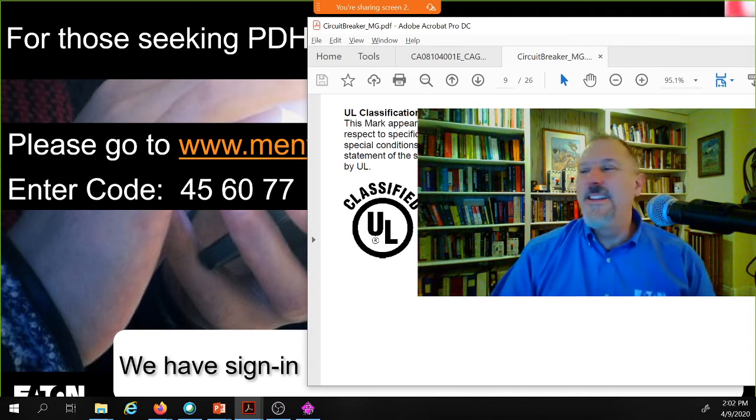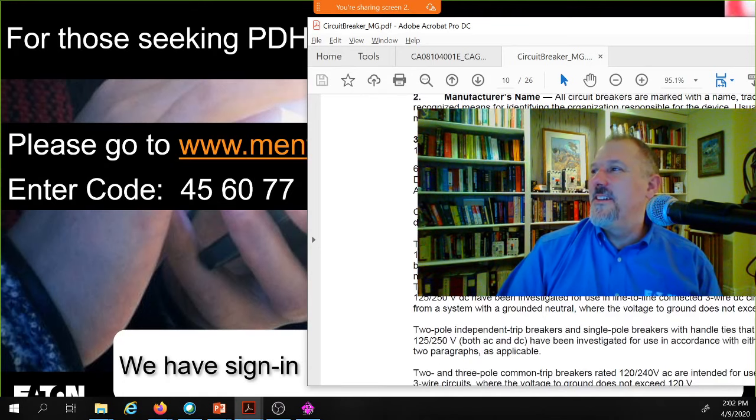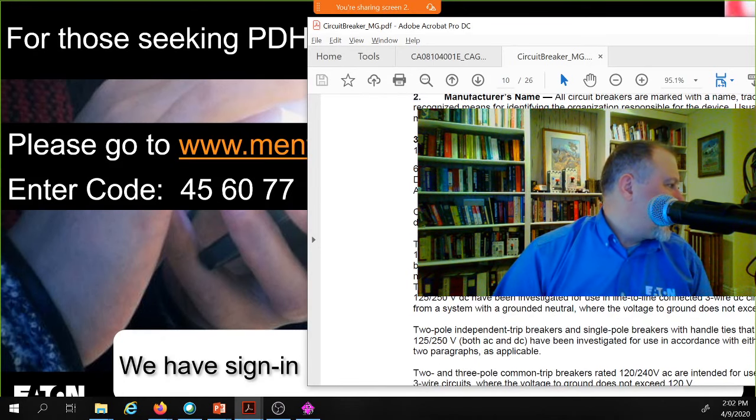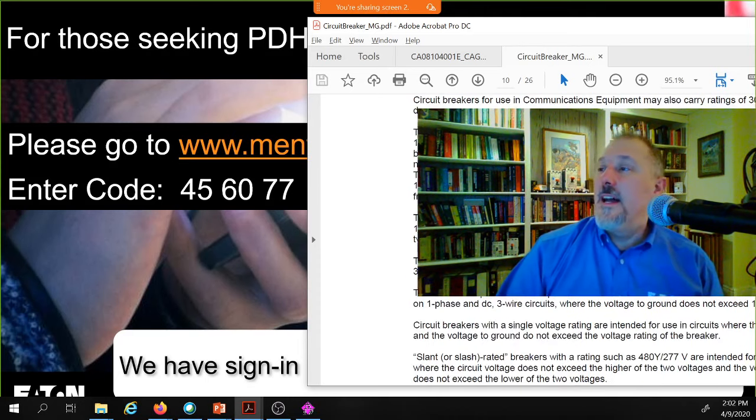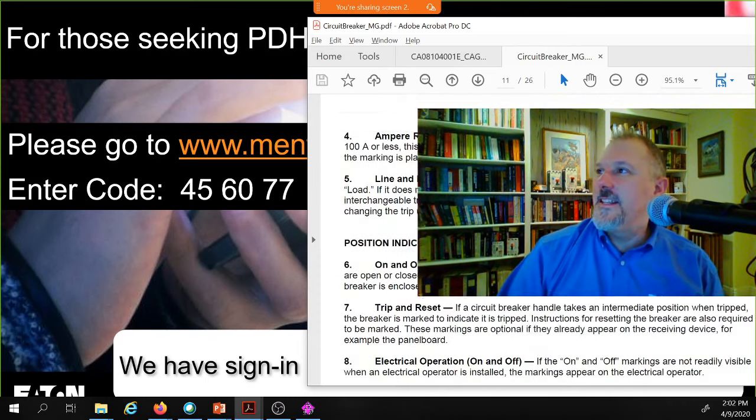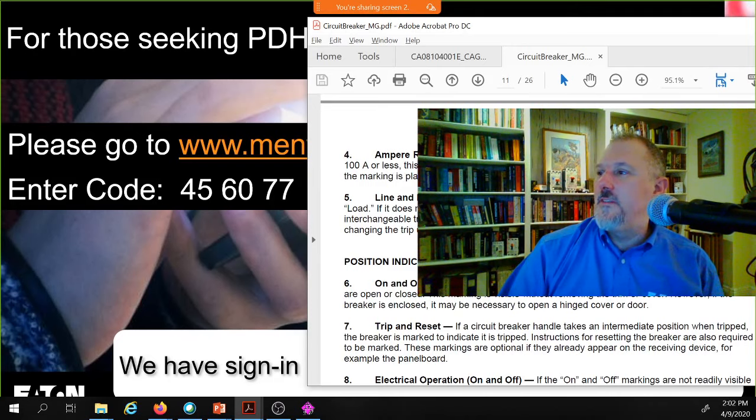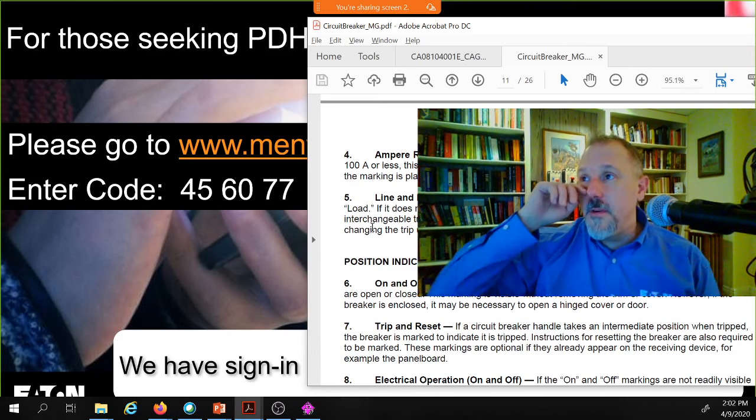Hey, thanks, Ryan. I just saw you come in on Facebook. I don't know if I was actually live streaming on Facebook or not, but in any case, ampere ratings, line and load identifications. Remember, if a breaker is marked line and load, then you can't reverse power feed through it.